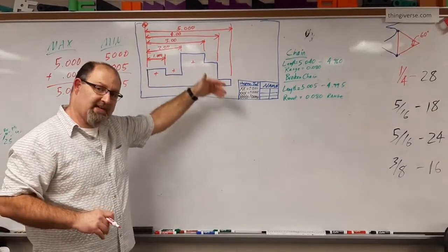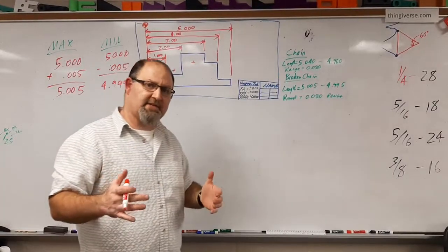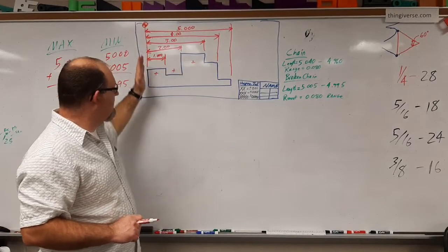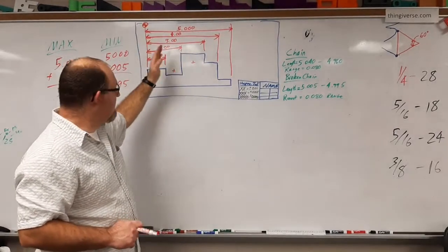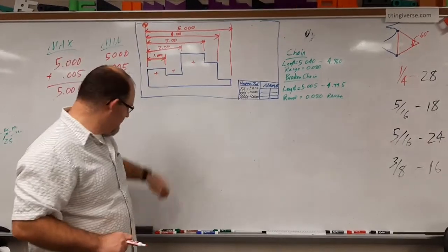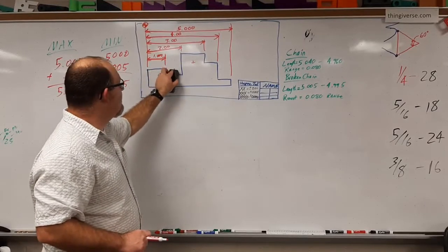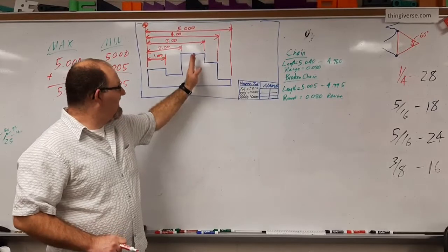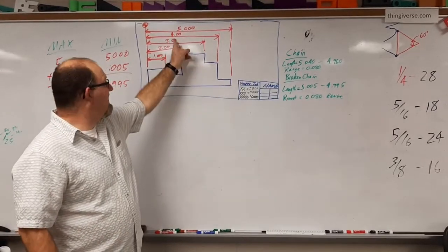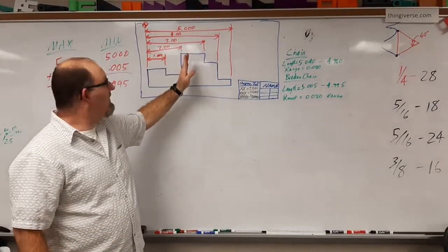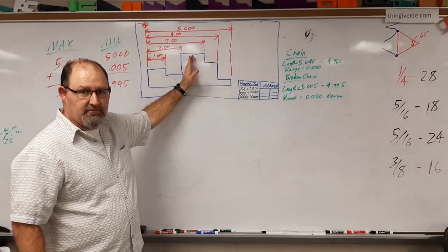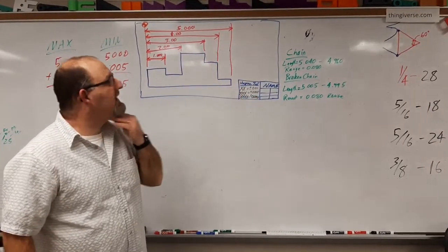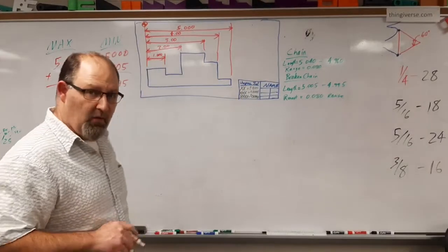So this part is actually going to have tighter tolerances, and this part is going to be all referencing this one edge, or at least for all these dimensions here. So we no longer have these tolerances here accumulating. Each edge stands on its own. So if we were to calculate, let's say the midpoint, it's still going to be the plus or minus 0.01 for that midpoint edge. Okay? Whereas with the chain and the broken chain, there's going to be more wiggle room.